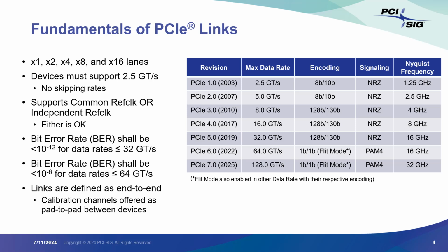One of the unique things is that PCI-SIG spec revisions build upon one another. Link training starts at slower data rates and then builds up to the max data rate that the system can support. These systems will often use different implementations of reference clock and other control plane features, so it's important that the interconnect, whether a cable assembly or a connector, supports the transmission of those signals as well as the high-speed signals.